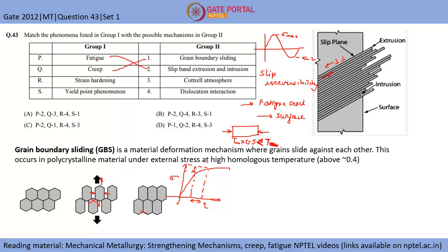As you are straining the material, the stress required to strain that material up to a particular point is basically the strain hardening. As soon as plasticity starts after the yield point of the material, the dislocations start to move. Basically the movement of dislocations is plasticity. When dislocations start to move, they interact with each other. Let's say this dislocation interacts and forms jogs. And as you know, jogs are a structure of two dislocations where they are pinned to each other.